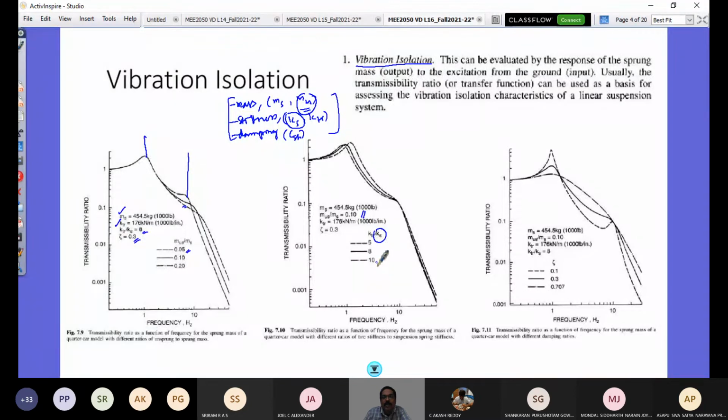For the soft spring, you see here at the low frequency range it is a higher value. At the mid frequency range as well as here it's negligible. So in the mid frequency range beyond this resonance state, you see this softer spring is better isolating. Why do I say that? For any given frequency, look at this value and this value. Here the value is very less compared to this value, because the log scale is 0.2, 0.3, 0.4, so it's more. So this value is preferred.